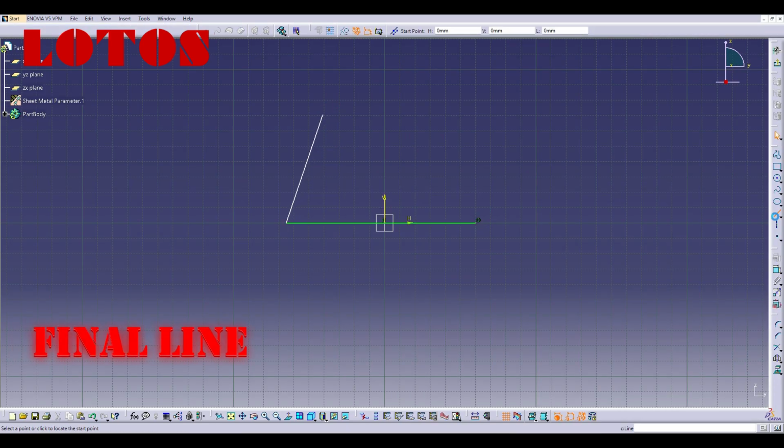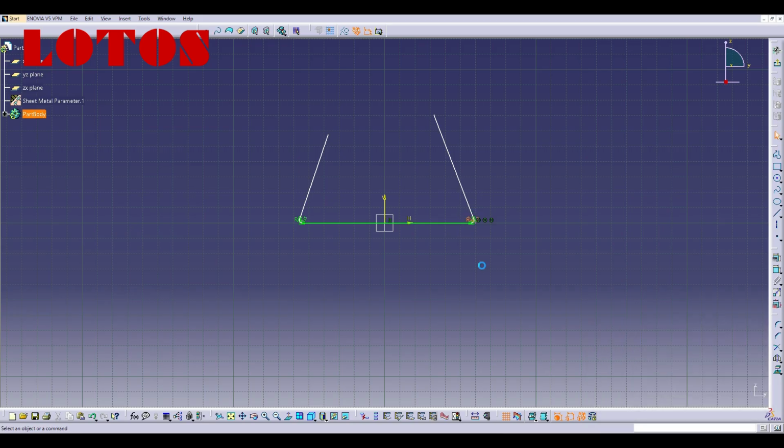In the final step, the profile is almost complete, and the sheet now has 2 vertical edges. We just need to bend it an extra 5 degrees to fully compensate for the springback.